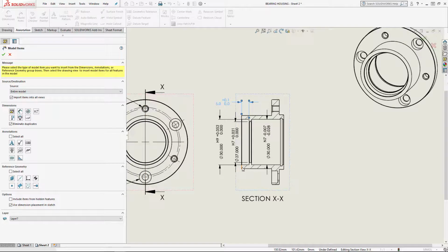But let's say when you're creating the sketch, putting that value in is not as useful as putting some chain dimensions in from here to this face, and then from this face to this face, and then from this face to this face. So in that instance, the way that you want to dimension the drawing isn't always exactly the same as the way that you draw the sketch, because the two have different constraints on how you dimension them.